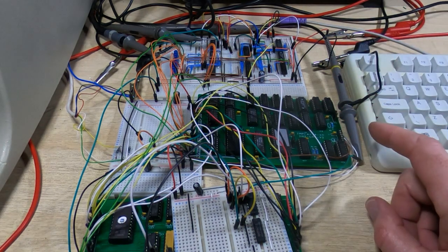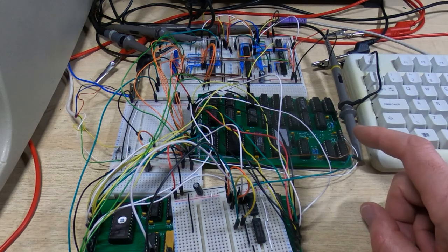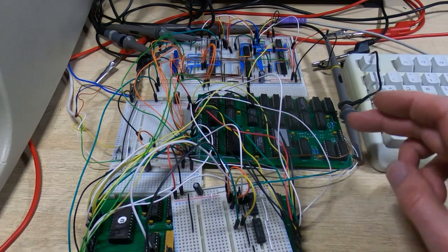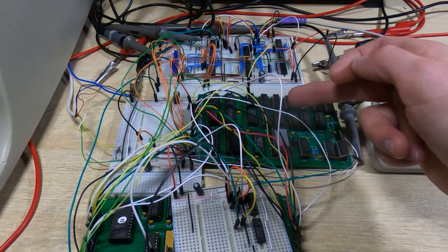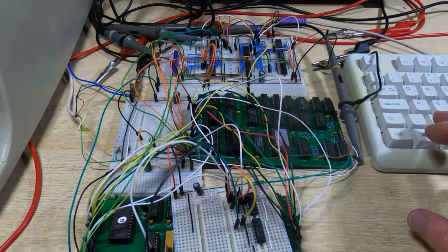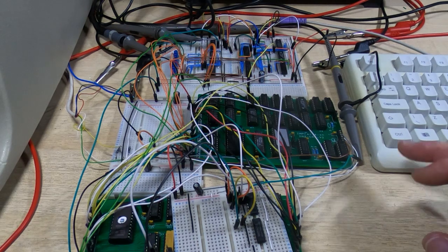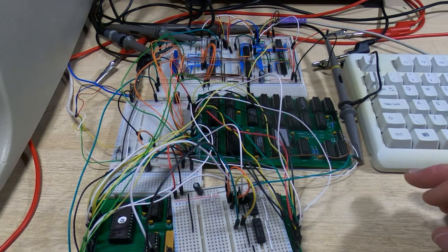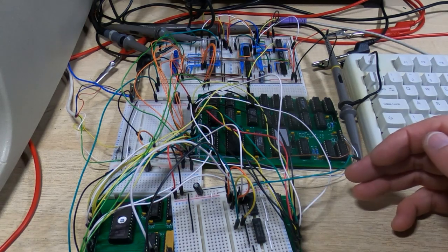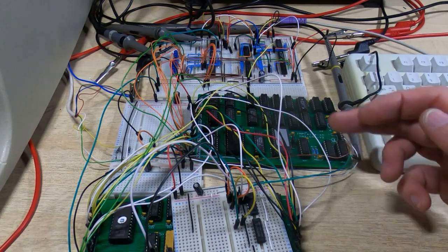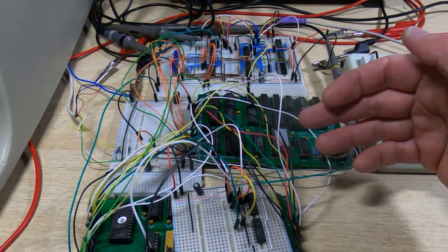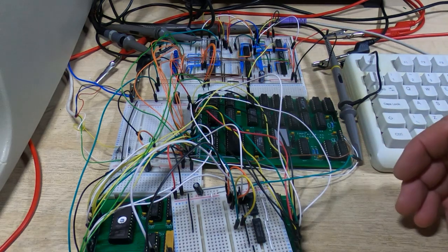However, one of the things we need for that to work correctly is to be able to read from the video RAM. It's okay if we're just typing characters in and we'll just set the bit as each new character comes along. But if we want to move the cursor around using the cursor keys, we need to be able to read the character from the screen RAM, because if we move the cursor into a particular location